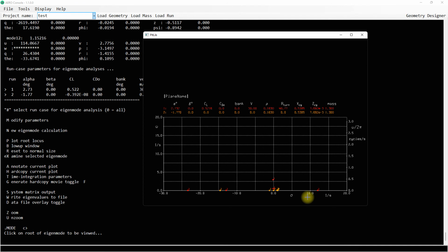If you remember, earlier we were analyzing the static stability of the aircraft, and we found that this aircraft was not statically stable. Because it wasn't statically stable, it would for sure not be dynamically stable, because static stability is a precondition for dynamic stability. So when we get to the analysis of dynamic stability, we see that we do have some unstable dynamic modes for this aircraft.